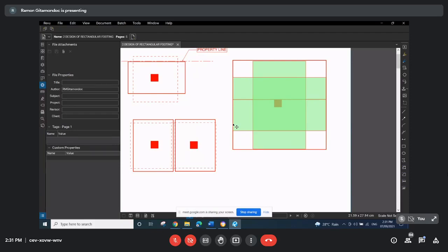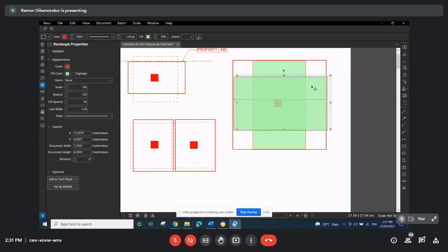For example, a finite element model will disclose it, because the software generates a stress contour or moment contour. You can color code them, so the higher moment values will be in red, whereas lower values will be in blue. So you can see where the bending moment is concentrated, and that is where you put more steel reinforcement.